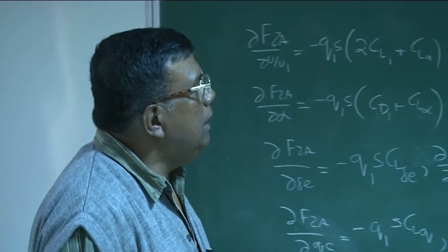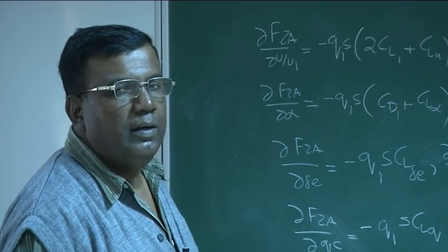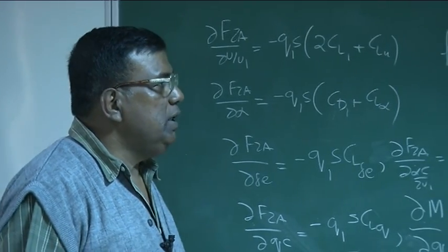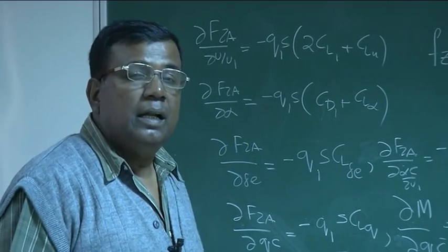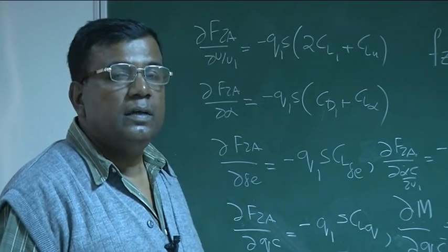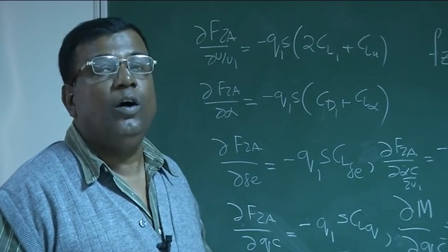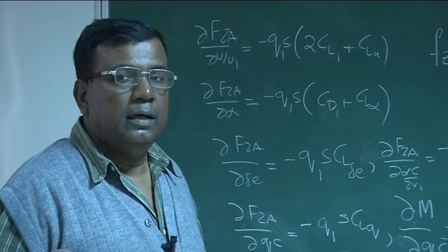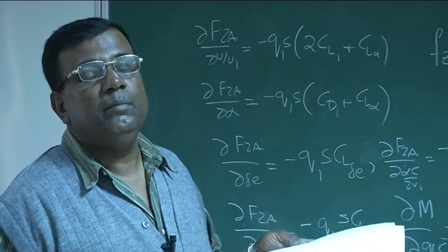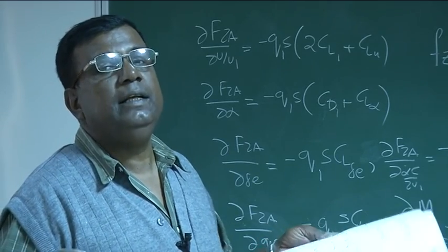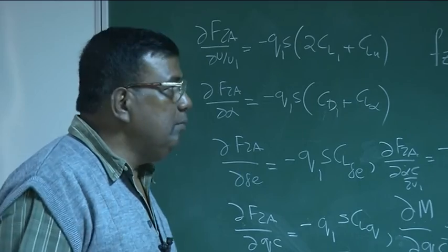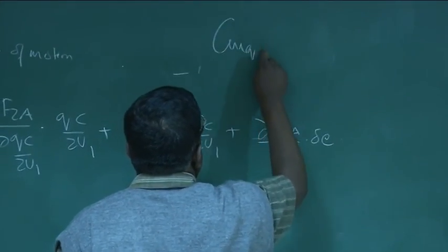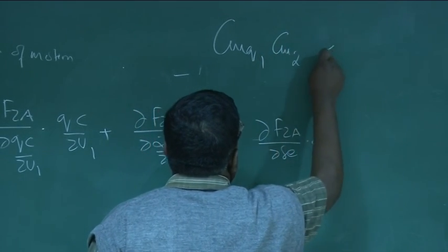We have seen how to understand what is Cm alpha dot, what is Cmq, what is Cl alpha dot. You could very well appreciate the sign of Cmq is negative and Cm alpha dot also will be negative, because alpha dot is coming because there is a lag in downwash primarily. So actually the tail at time t is seeing more angle of attack, because the downwash is happening only at a time later than time t by Lt by u1. So that will also give a nose down moment. So Cmq and Cm alpha dot both are negative. Cmq and Cm alpha dot are less than 0.